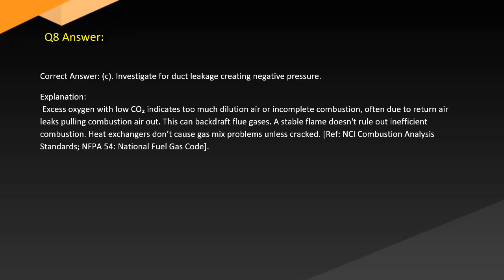Answer. Correct answer: C. Investigate for duct leakage creating negative pressure. Explanation. Excess oxygen with low CO indicates too much dilution air or incomplete combustion, often due to return air leaks pulling combustion air out. This can backdraft flue gases.